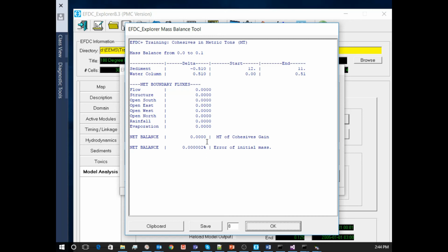But if you had a potentially significant groundwater source, then you might need to reconsider how you're putting that in. Maybe it is groundwater. Or it could still be measurement error. Or maybe you need to account for evaporation because you're doing Lake Mead, and water is leaving rapidly from your system. So you've got to use your engineering and scientific background to interpret how to proceed.